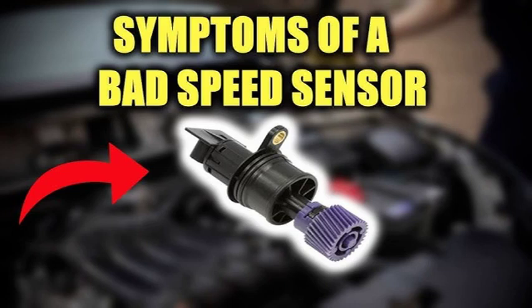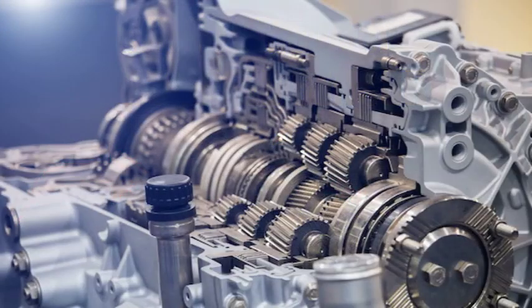What are the possible causes of the P0720 code? The most common causes of the P0720 code are a faulty VSS, a damaged VSS wiring harness, a loose or corroded VSS connector, a problem with the PCM.